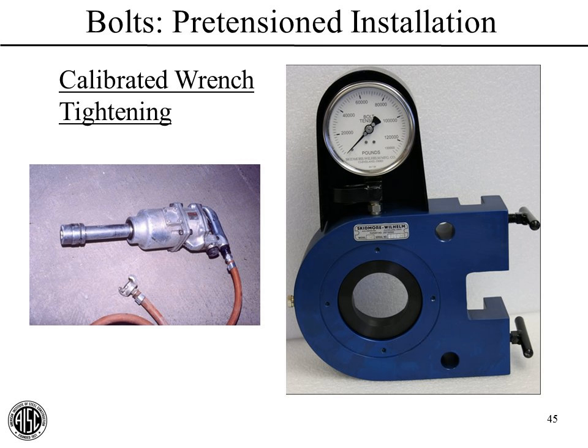Okay, the calibrated wrench method. In this method, whatever tightening device that's going to be used, like this impact wrench we have here, will be calibrated on site using a device like this, a Skidmore-Wilhelm calibration device that reads the force up there. And once these wrenches are properly calibrated, they will shut off once they achieve the desired pretension.